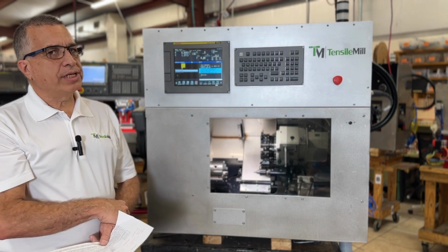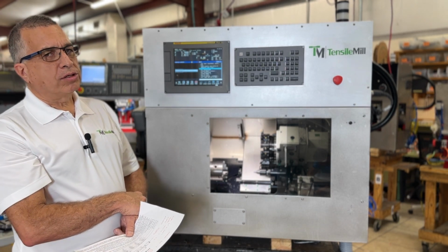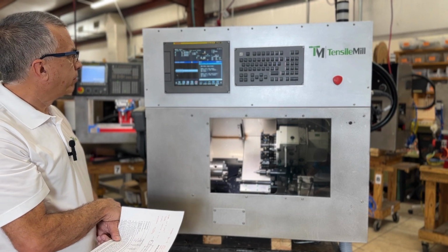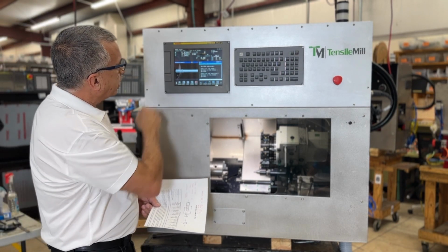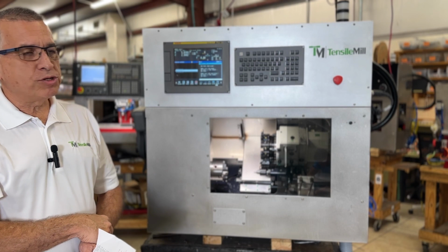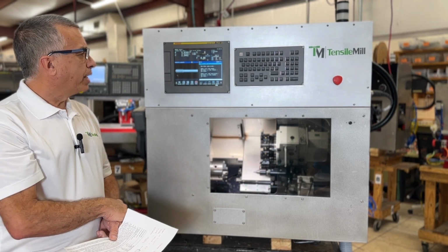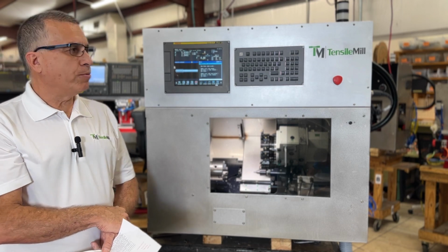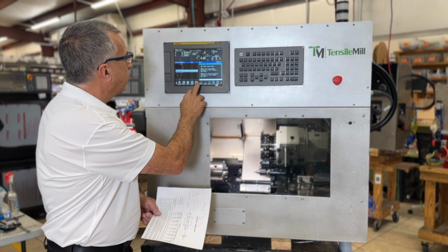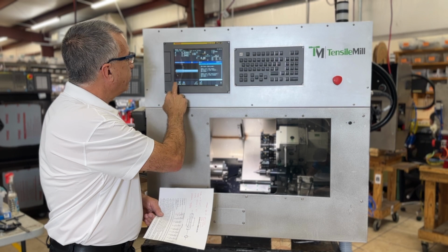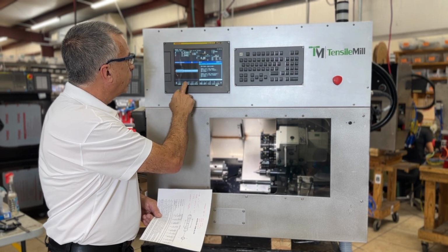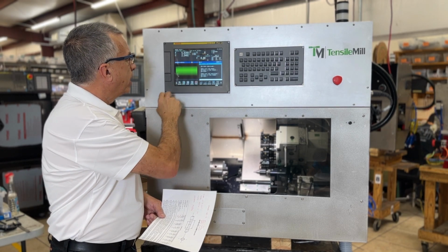And then after the thread, it's going to do the cutoff there. Now you see that the part does the cutoff, but it doesn't finish doing the cutoff. It leaves about 0.1 inch diameter, so we can cut it off with our hand. So we go to the initial view, photo, and then we can resimulate.